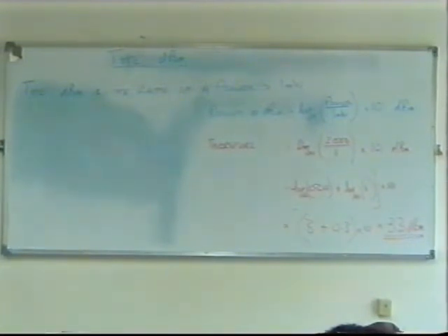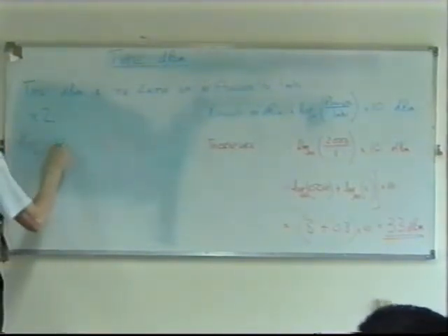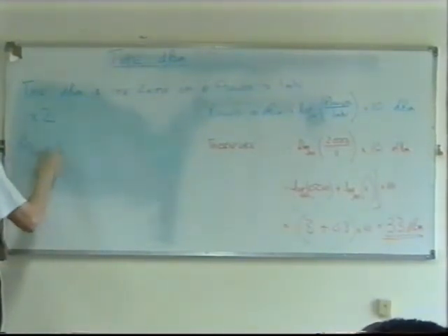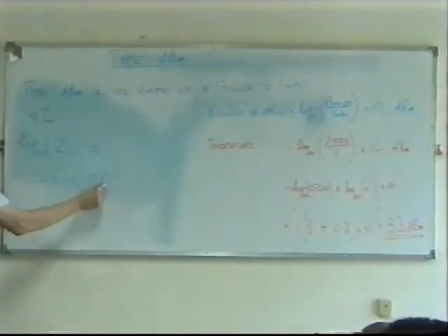If you double the power, it means you multiply by 2, doesn't it? So the ratio is 2 to 1 between the old power and the new power. So the dB is the logarithm to the base 10 of 2, and then you multiply that result by 10. Now, what did we say the logarithm of 2 was? Yeah, 0.3. It's a number between 0 and 1. So that becomes 0.3 multiplied by 10, plus 3 dBs.